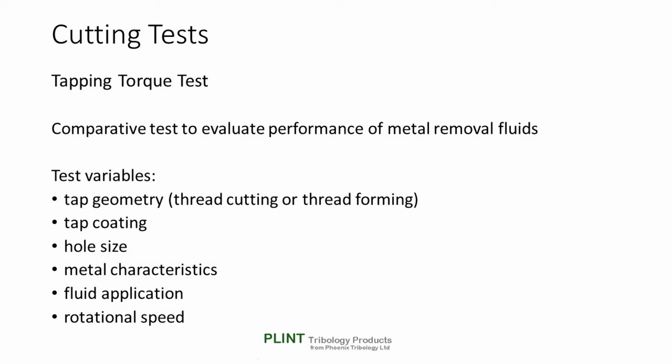Substantial work had to be done under ASTM to arrive at a test that has a good repeatability. Specimens must be extremely repeatable. Taps must be qualified, which means that only taps that fall within a certain error when testing them in a reference fluid may be selected. Only then are differences in performance, which may be as small as 1 or 2%, measurable. It makes the test tedious and expensive, but is to date the only ASTM laboratory method for cutting performance.